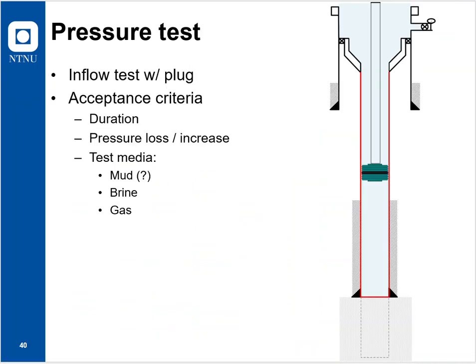Now, there are a few other things that you need to know as new drilling engineers and professionals. Pressure testing. There are some aspects like inflow testing with a plug. You have heard about it, I guess, and acceptance criteria. Typically, the duration will be discussed, and how much loss or increase will be accepted.